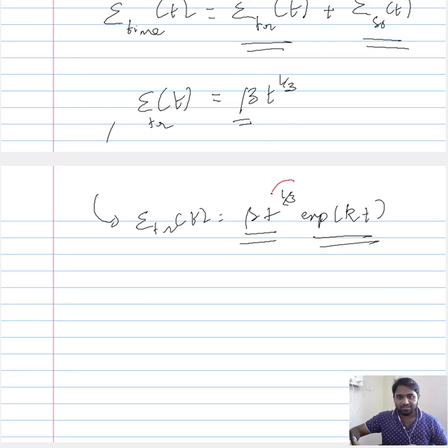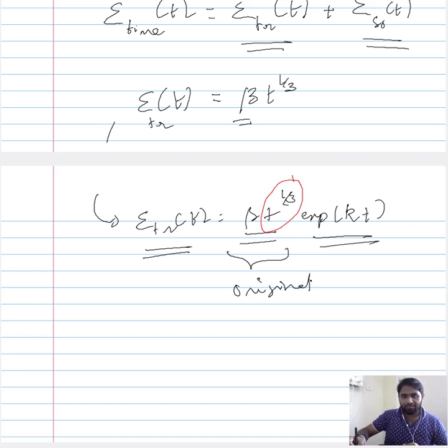Since we have combined, subsequent to the expression given by Andrade, the transient stage and the instantaneous creep, the recent expression for transient creep would be of this form. The recent expression includes the original approach of Andrade and the new inclusion, because the transient creep is part of stage 1.